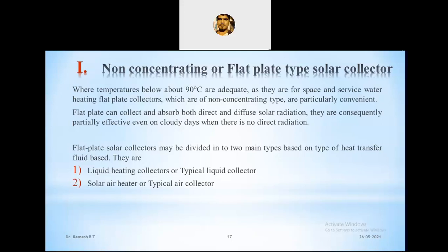The flat plate can collect and absorb both direct and diffuse solar radiation, so it is partially effective even on cloudy days when there is no direct solar radiation.